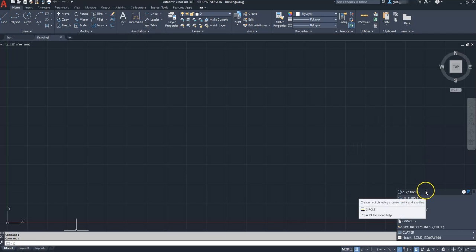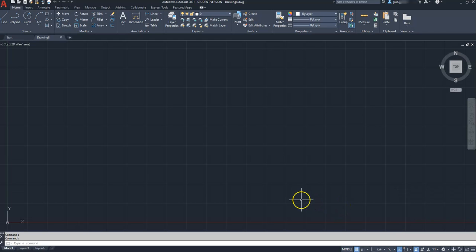And there's a couple different ways that I can accept this. I can come over here with my mouse and click on circle. I could also hit enter. You're going to find as you go through and as we do a few more of these commands that there's, again, more than one way to do things. So that's one way to grab a circle. And if we go back to our ribbon up top, you'll see that in our Home tab, we have a circle button here as well. Okay, so I just wanted to call out two different areas where you could possibly start putting commands into AutoCAD.